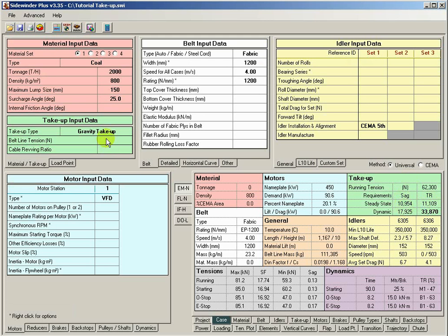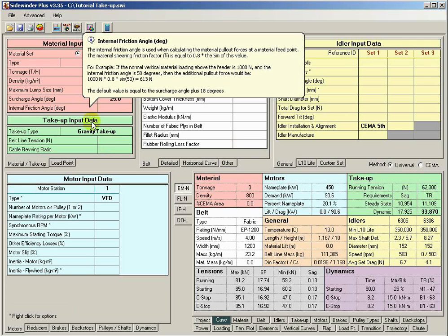Now, I also want to point out that when you're working with a conveyor file, entering and knowing your take-up tension is crucial. The take-up system is essentially the heart of your conveyor. No different than the belt width, belt speed and rating, we can leave all these variables blank, but as you progress with the conveyor design and as you nail down your design, you want to start entering these variables so they aren't floating all over the place.